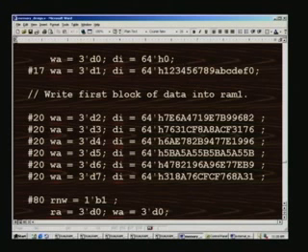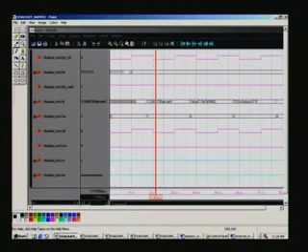Let us see whether the waveform conforms to that. So the first waveform, I will first read out before zooming. You have a PCI clock here, and byte enables, all of them are forced to FF, that means it is all ones here, and you have a DIN valid asserted, so 1 here, and data is changing at every 20 nanoseconds, and to start with it was 0 there, so that is precisely what has appeared here, and then we had written 1 2 3 4 up to F0, you remember.